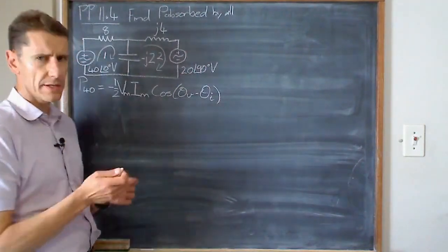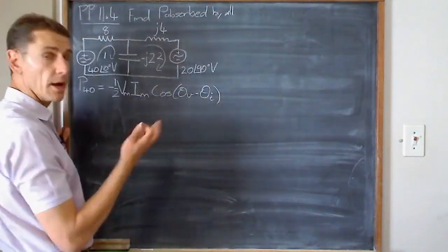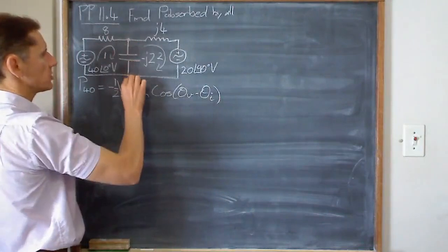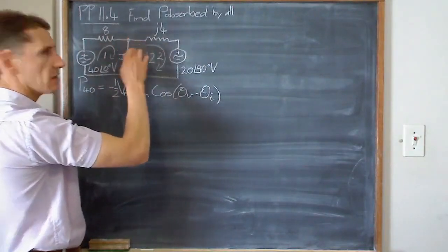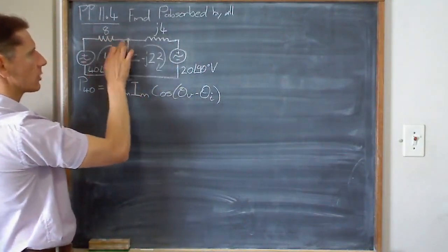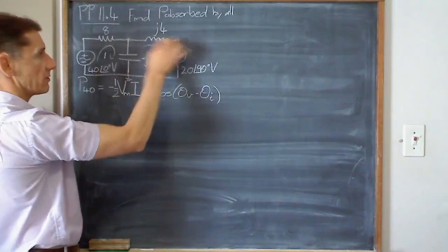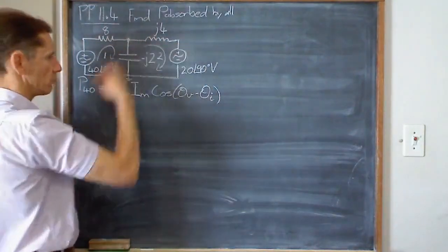But either way, let's stick with the mesh analysis, otherwise I have to redo my notes. Perhaps make this your reference node over there, and make that VA. Solve for VA, and then Ohm's law gives you that current. So one unknown gives you both currents.